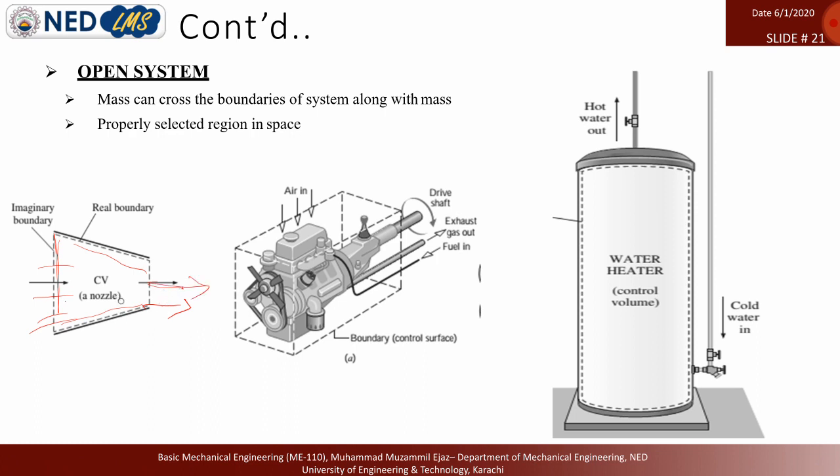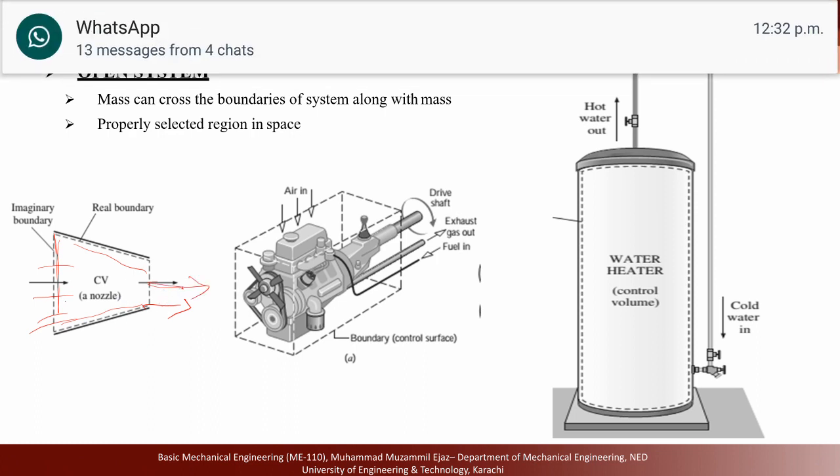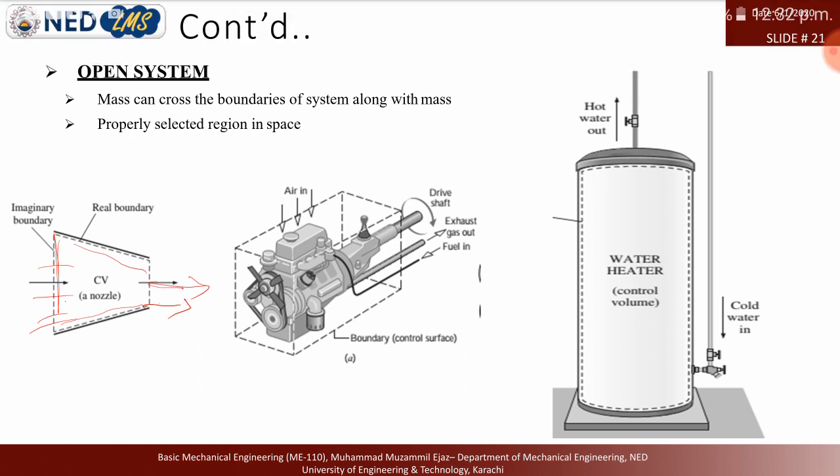And that resultant velocity, by the third law, every action has an equal and opposite reaction. So by this exhaust of high velocity gases, this nozzle or connected turbine moves in this direction, by which the plane is flying. So it's an application of an open system: both air and fuel come into the combustion gas turbine, and exhaust through the nozzle with high velocity to move the gas turbine engine in aeroplanes.